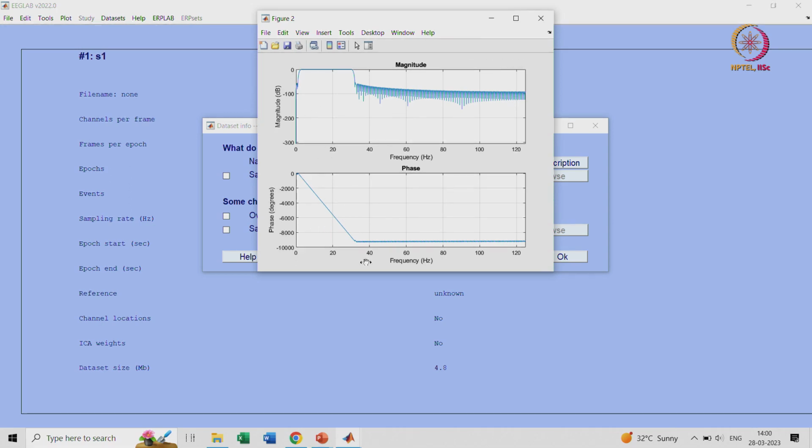So it should be linear phase. Also you can see in this particular range your gain is 0. Now 0 means your signal will get 0? No, the dB is 0. When dB is 0, log of something is 0, which is 1. So it will allow the signal with the gain 1, whereas other signals you can see are getting attenuated by at least minus 60 or minus 70 dB, which is a huge contrast. So it will allow the signal only within this particular range, okay.